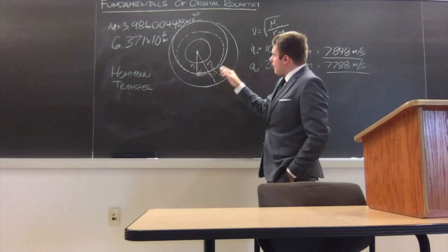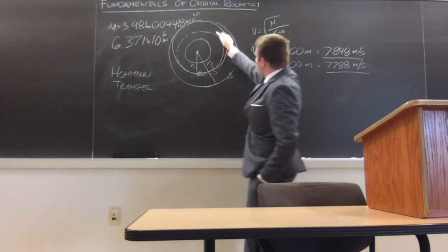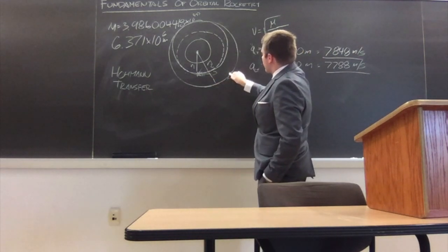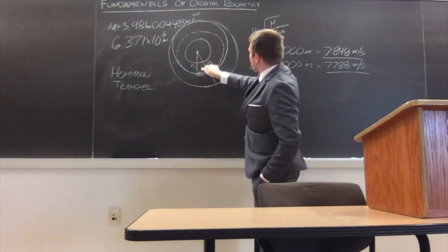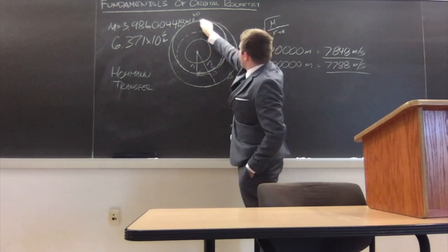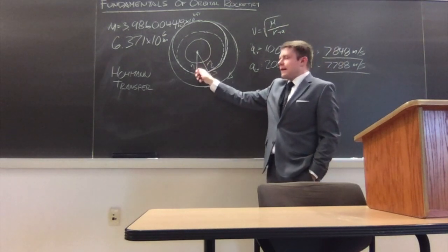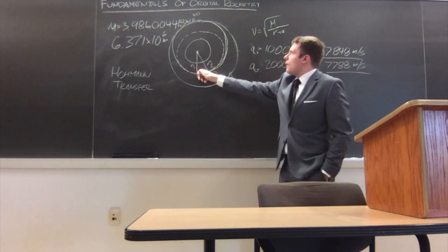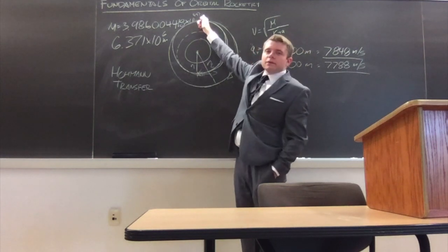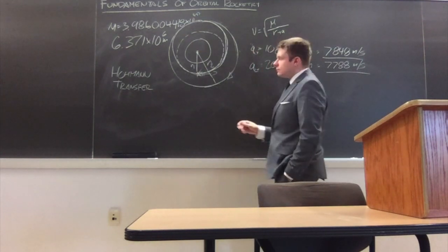So how do we quantify this then? How do we know what position the target has to be in so that it'll cross this distance in the orbit at the same time we cross this distance in our orbit? Because again, we go back to the lecture from apoapsis and periapsis. We are functionally going to be at the periapsis of this orbit, and we want our apoapsis to match the orbit of the target vehicle.